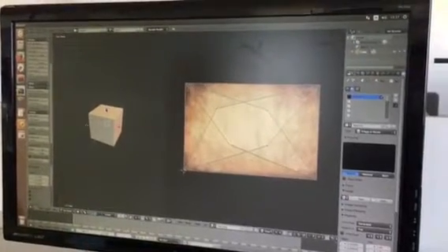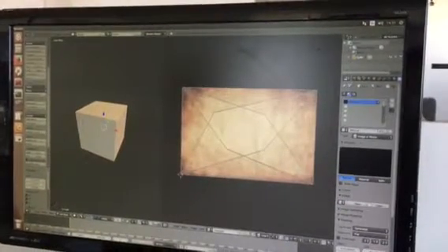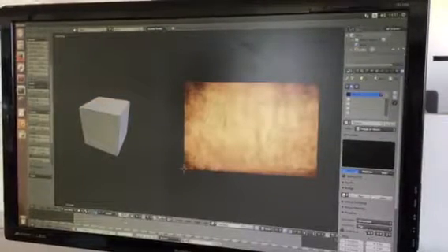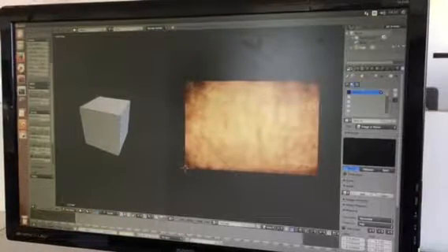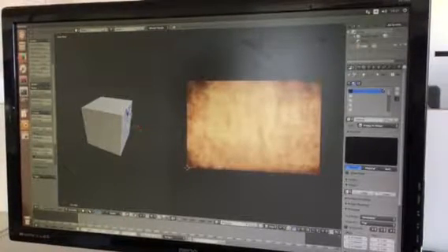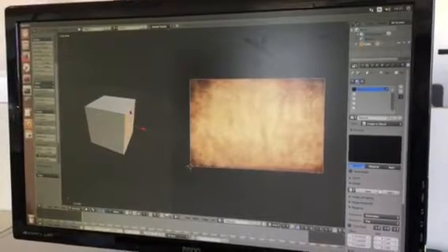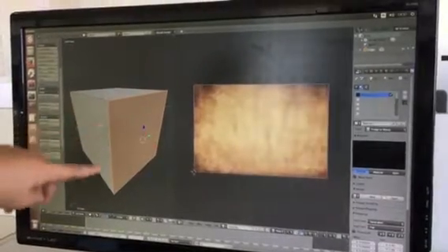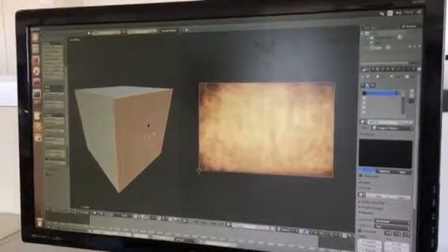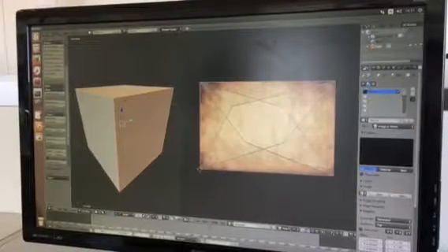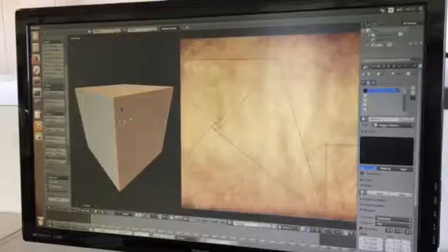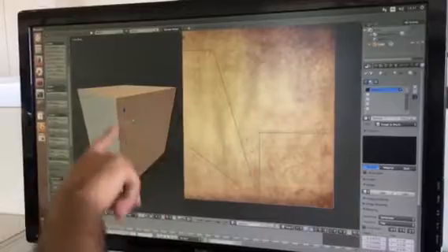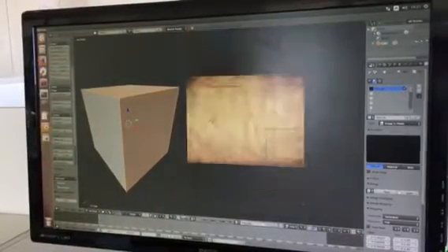Or you could also do what we call marking a seam. So to mark a seam, you first make sure that all faces are unselected, and then you click on edge selection here. And with the right click of the mouse, you start selecting the 4 edges. And then you mark a seam. By marking the seam, this already turns a bit red. So once you go again into face mode, select all faces and unwrap again, it will unwrap in a more smart way. So this face is this one here, and all the others will be unwrapped automatically for you.